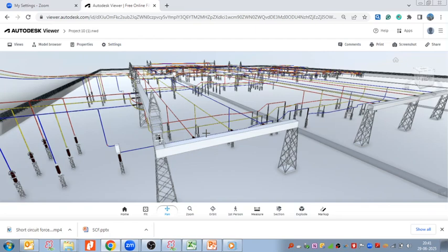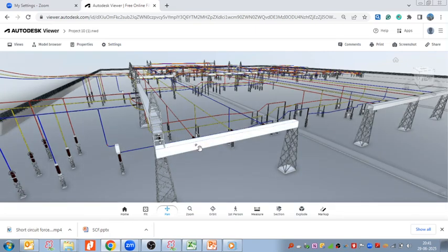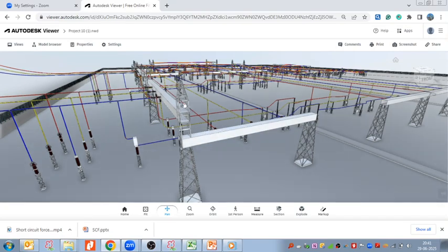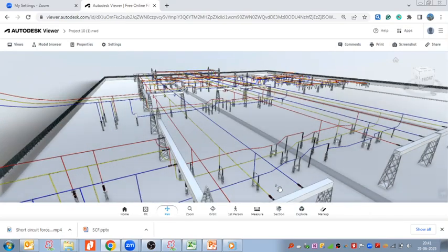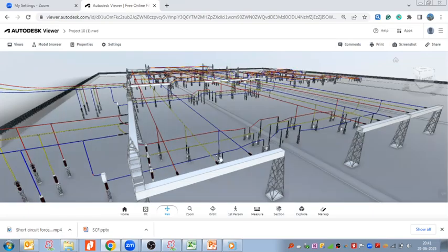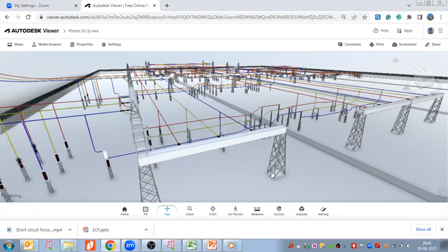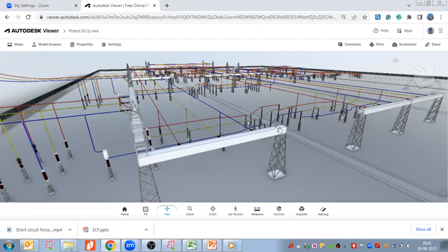But before performing this calculation, the civil structural engineer will ask you for some input, so you have to provide that input. They need to consider what conductor weight is coming on this, what conductor span is coming on this, what should be the height of this gantry above the ground, or the beam, and what type of tower we are proposing, with peak or without peak.